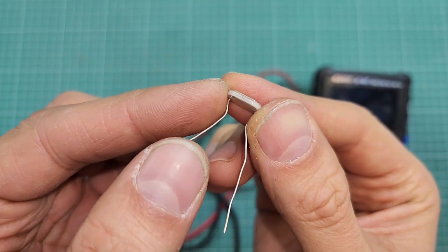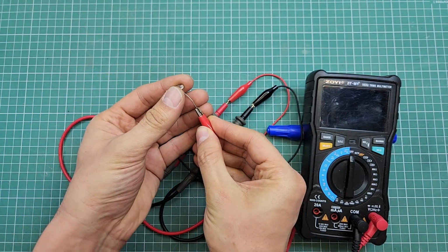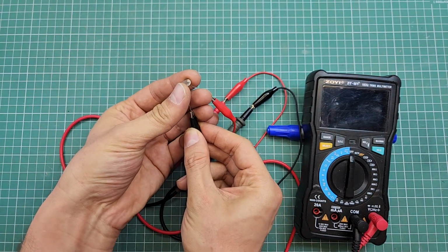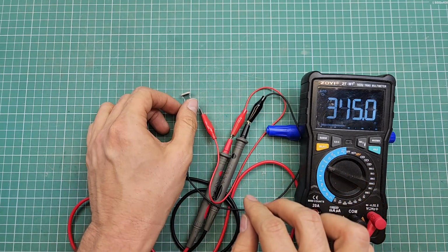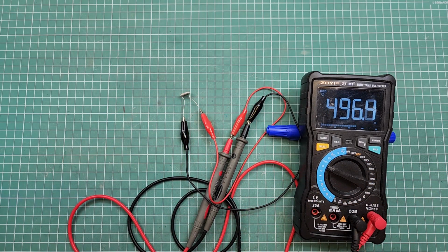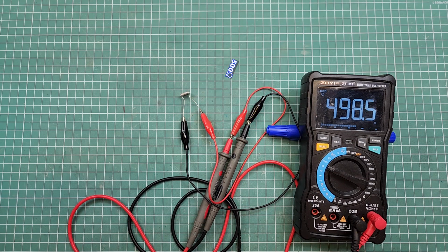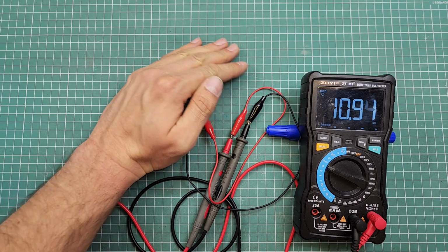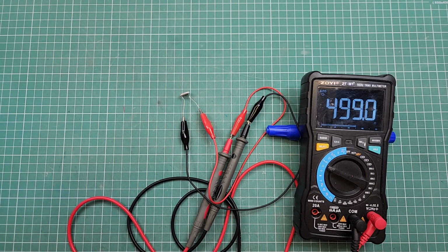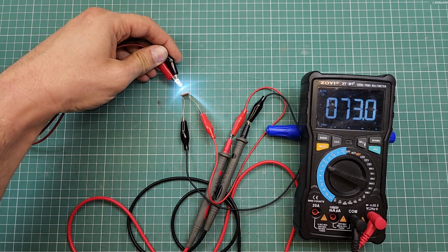If I connect the 2 pins of this component to a multimeter and set the multimeter to resistance measurement mode, you can see that the multimeter shows a value. Right now, the resistance between the 2 pins is about 500 ohms. Now, if I block the light from hitting the LDR by putting my hand in front of it, you can see that the resistance between the 2 pins increases, and conversely, if I shine more light on it using a light source, you can see that the resistance between the 2 pins decreases.